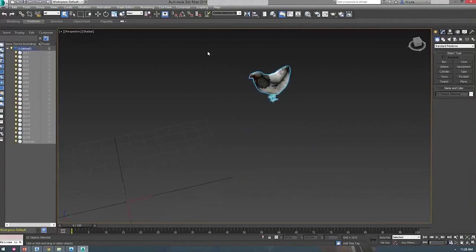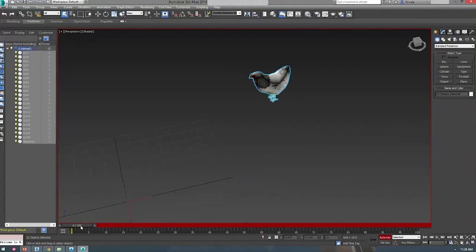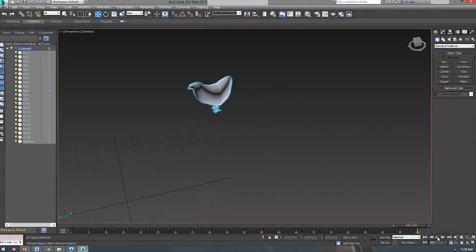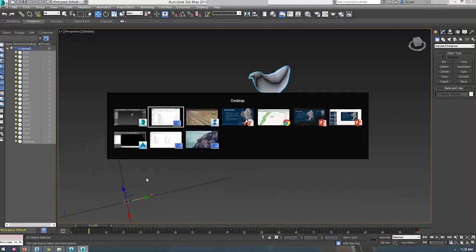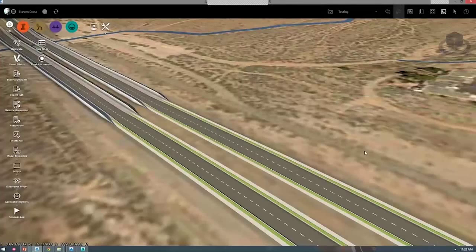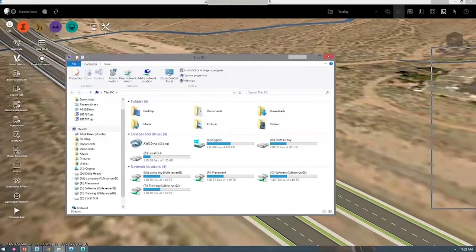I can simply select the entire object, turn on auto key, slide over that information, and use the move icon to key in the next location of that object, and then uncheck auto key, and hitting play would give you some sort of animation. Now, this can be any sort of linear or relatively simple animation, and what you end up with is if I simply brought in that animated object, right?